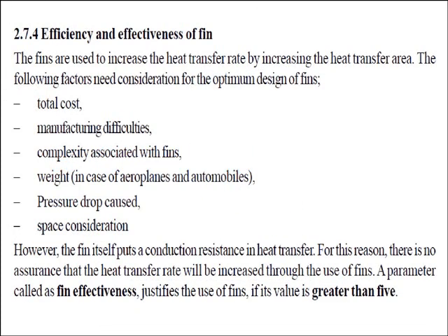So friends, we know that fins or extended surfaces are used to enhance heat transfer as they increase the total heat transfer area. When we design or install a fin, we have to go for an optimum design, and during this design we have to consider the following factors: the total cost, manufacturing difficulties, complexity associated with the fins, weight, pressure drop, and space consideration.